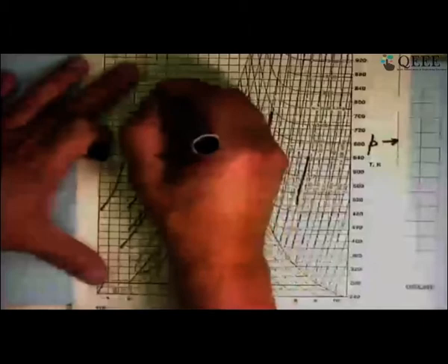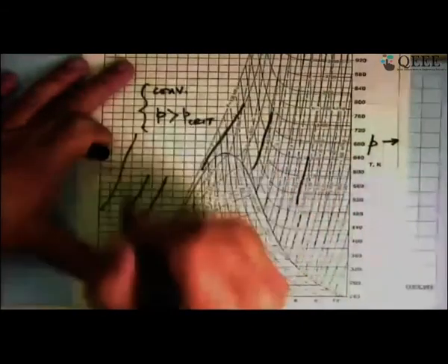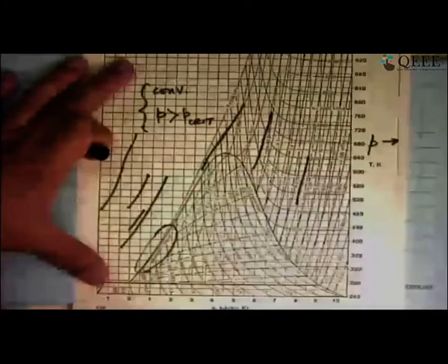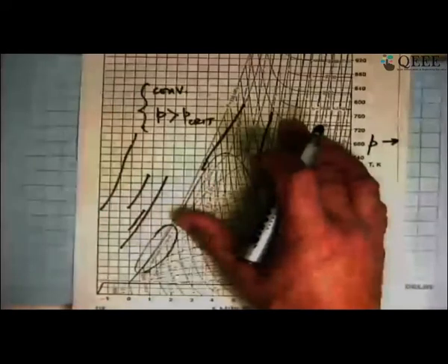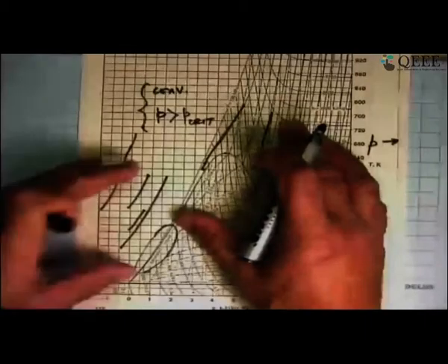or some would call it a superheated vapor. Well, in this case, we would still apply the principles of single phase convection, what we have learned so far, but the relations that we have developed would have to be applied with a little bit of care in this part, and there are specialized correlations specifically for supercritical heat transfer. So we will have to use those. The difference is that as it goes from here to here, there is no discernible change between the liquid and the vapor phase, which is what we see in boiling and in condensation. So that doesn't happen here.